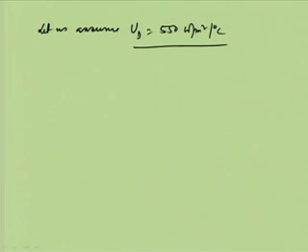Some initial estimate is needed just to get a preliminary estimation of the overall area, and then getting the number of tubes, the shell size, the tube size calculations, all these things to be done, and then finally recheck whether the initial assumption is correct or not. So, the UD is assumed first, that is just 550 watt per meter square per degree centigrade. This assumption is based on the kind of process fluids we have.